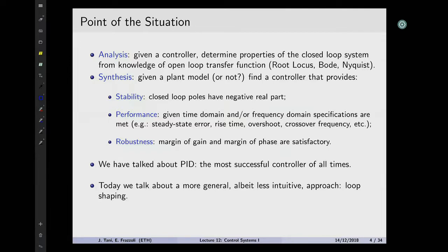We saw the Nyquist plot that showed us, through this weird Nyquist criterion that involved encirclements of some critical points, if the system was not stable. And from the Nyquist plot, we saw even how to measure interesting parameters defining robustness, like the margins of gain and phase. And we looked at the Bode plots, which are ways to represent the frequency response of a system. And again, we saw in the Bode plots where to look to find these important margins that determine robustness criteria.